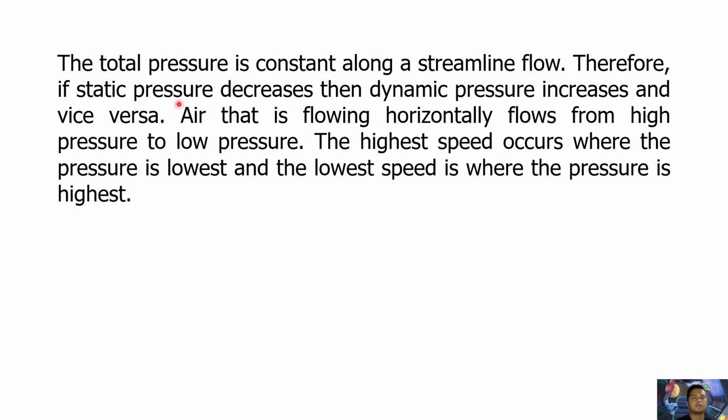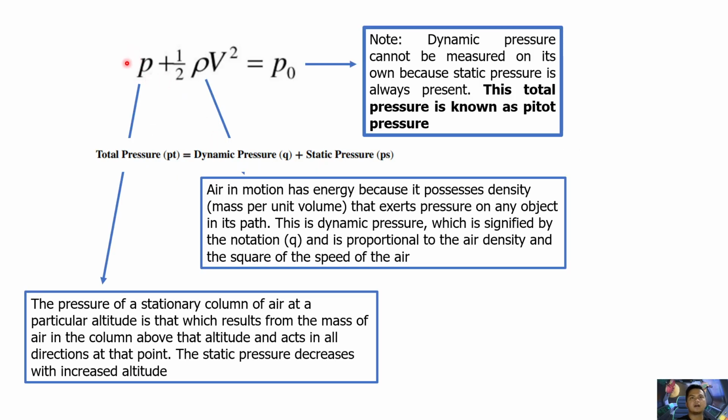So be mindful that when the static pressure decreases, the dynamic pressure increases. Kasi nga, di ba, if you can remember, Bernoulli's equation states that pressure plus 1/2 rho V squared is equal to a constant. So that's why if static pressure increases, dynamic pressure must decrease.